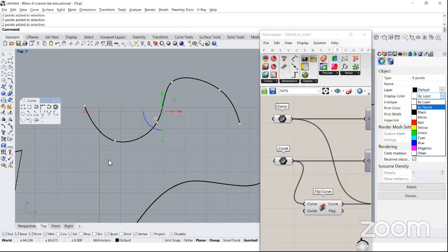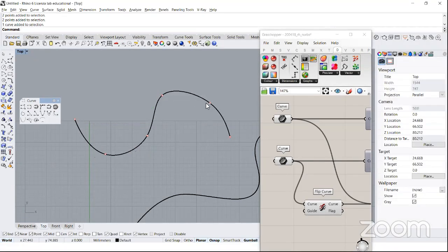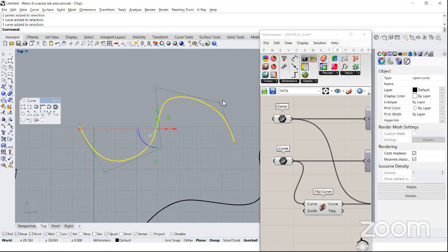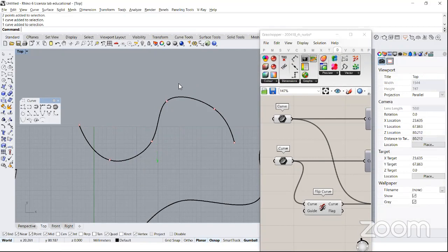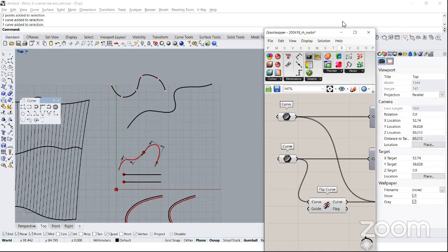And here are our control points that have no evident relation with the knots. So it's difficult to adjust this geometry based on the actual structure of control points, because we were not controlling the position of the control points. Okay, so try and work with control point curves, because it's the best thing that you can do.